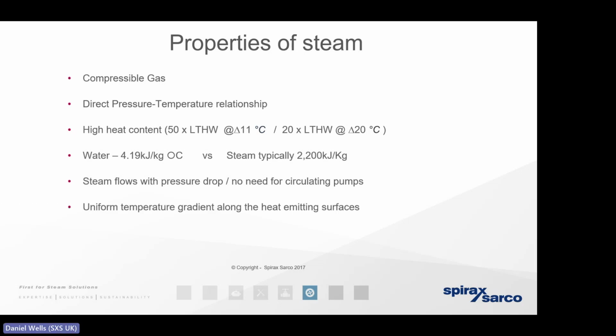And we know that when we depressurize the steam at the heat exchanger, if we depressurize the steam from a higher pressure to a lower pressure, it's going to expand. And as that steam expands, it's going to occupy every corner of that heat transfer surface area evenly and uniformly. And that means that efficient use of the heat transfer surface area, well, it means that we're not at risk of the cold spots or the striations as we commonly see with water-to-water heat exchangers.